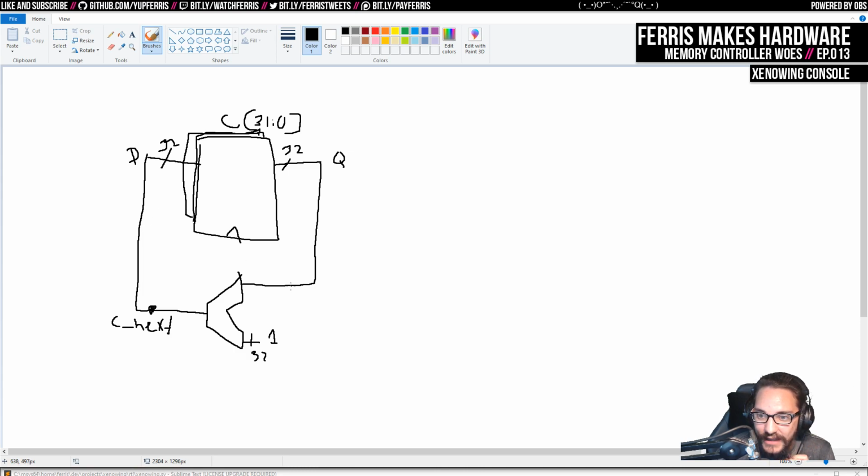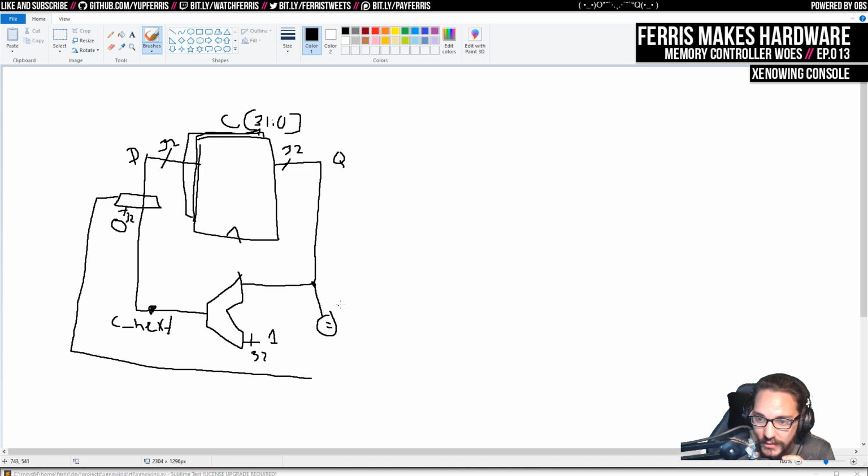And I have that logic here. So I essentially have a mux, where one input is this, and the other input is 0. For the selector of that mux, I have an equals block, and I compare this value, I know this is getting kind of confusing, to 1,000,000 minus 1, which is also a 32-bit value.